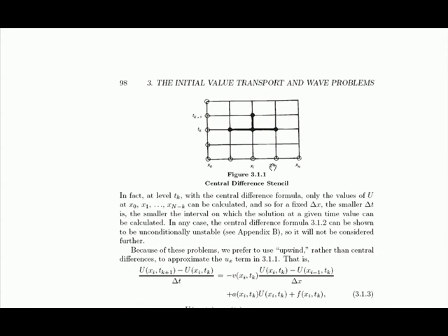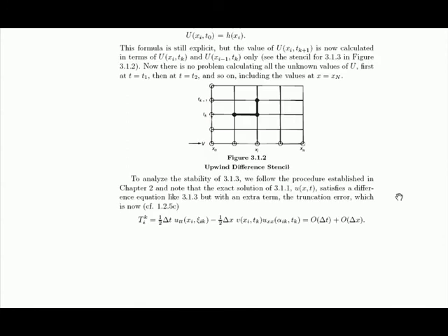So we're going to concentrate on the upwind difference method, which makes sense physically. We're trying to predict the temperature here at future time based on the temperature here and upwind. That makes a lot more sense, and as far as the calculations, it makes sense also because we're calculating this value based on these two, this based on these two, this based on these two, this based on these two, and we can't calculate that, but we don't need to.